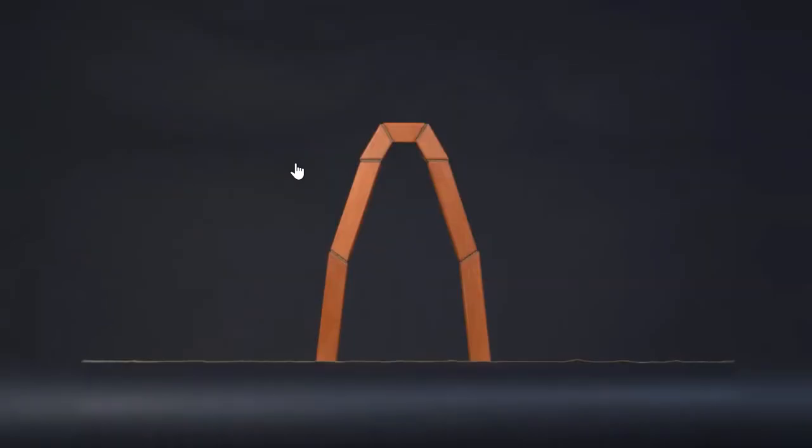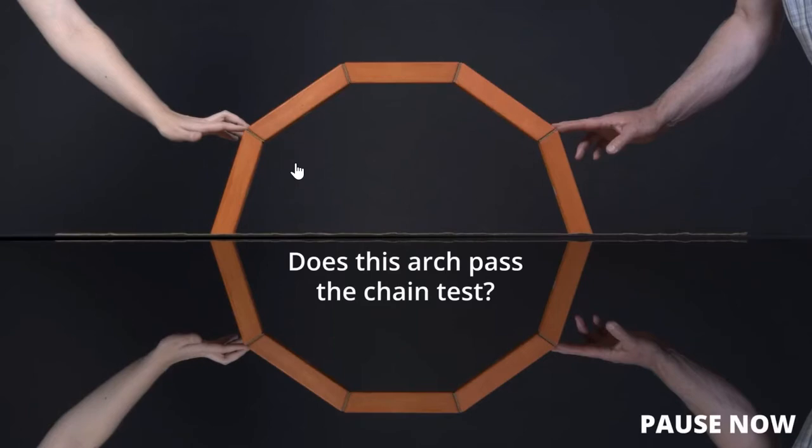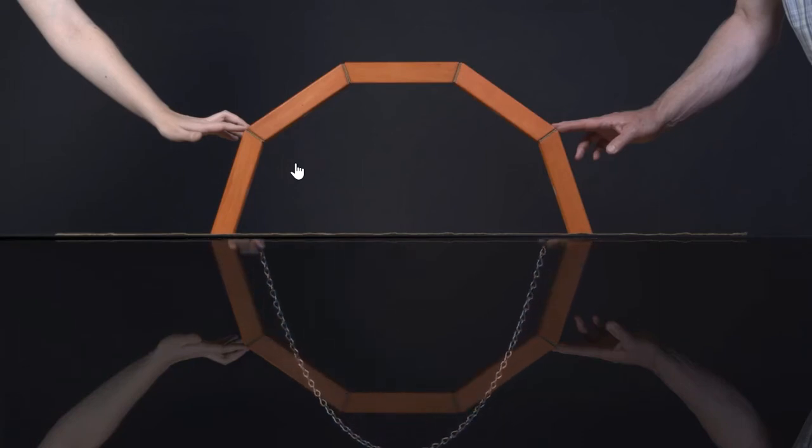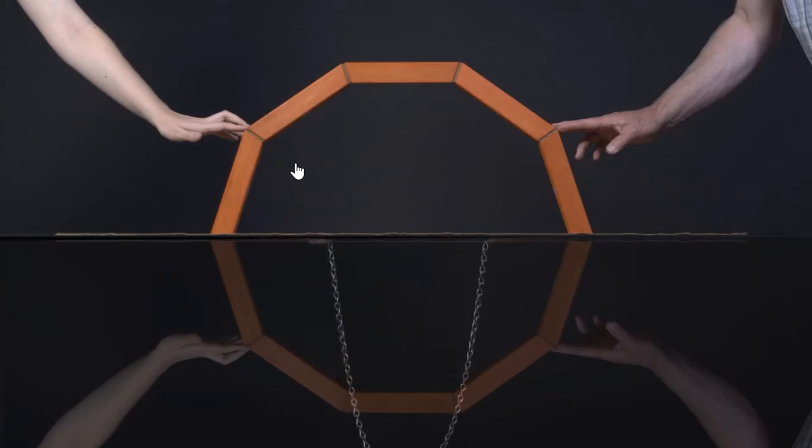Well, suppose you want to evaluate a particular arch design. If you can hang a chain entirely inside the profile of that arch, then it is a shape that can carry its own weight. We call this the chain test. Does this thin semicircular arch pass the chain test? It does not, because it is impossible to position a hanging chain so that it lies entirely inside the profile of the arch, and that is why it collapses.